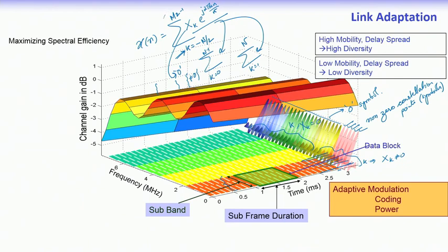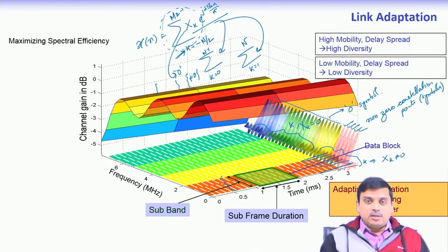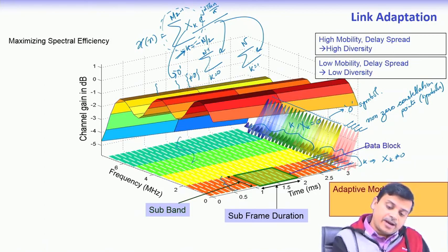That when we are adding these up over a smaller set, then the peak to average power ratio is automatically reduced. So, if the system allows the user to use only a small subset of the entire bandwidth, in that case the peak to average power ratio is automatically reduced for that particular user, right, because that user is not accessing the entire band.